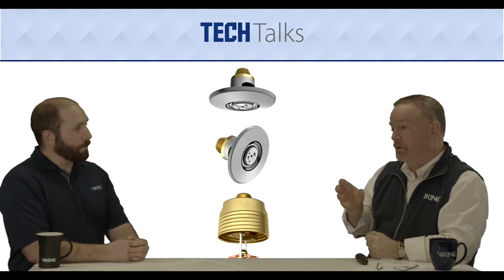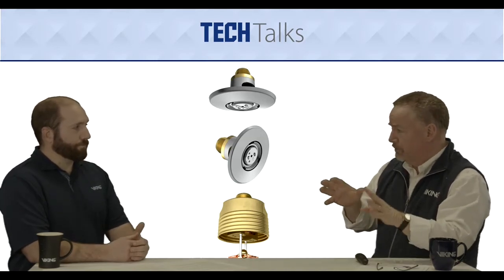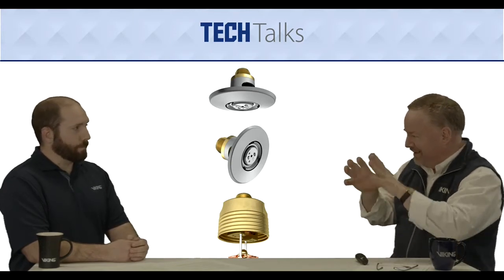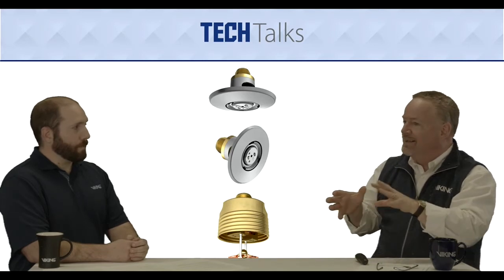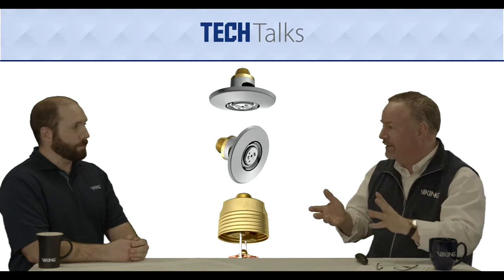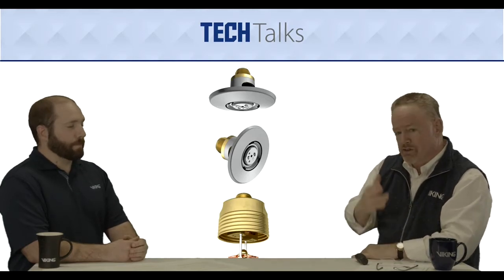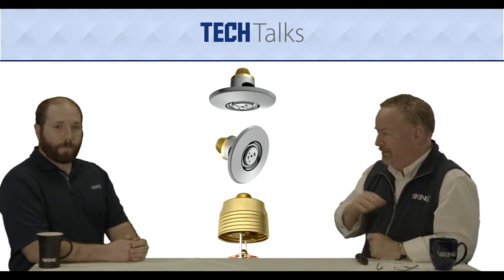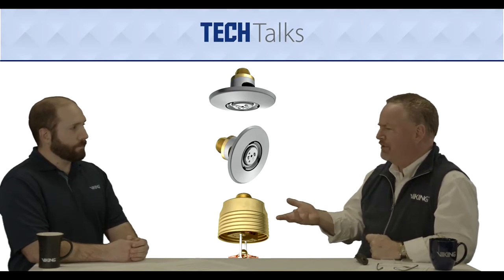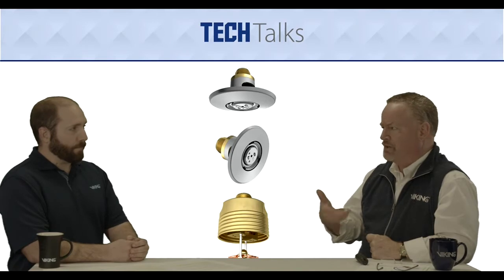Okay, so just a standard spray or sidewall, whatever it happens to be, but it's more about the occupancy that it's going into, right? It's all about the space that it's protecting, not about any special spray pattern that it's developing. Right, correct. The same thing would go here at the bottom. We've got our MRI, or non-ferrous type of sprinkler. Same deal there. It's evaluated under the same parameters.